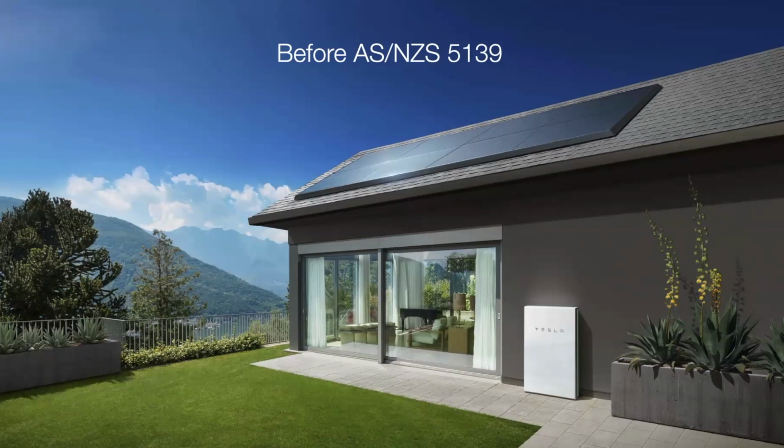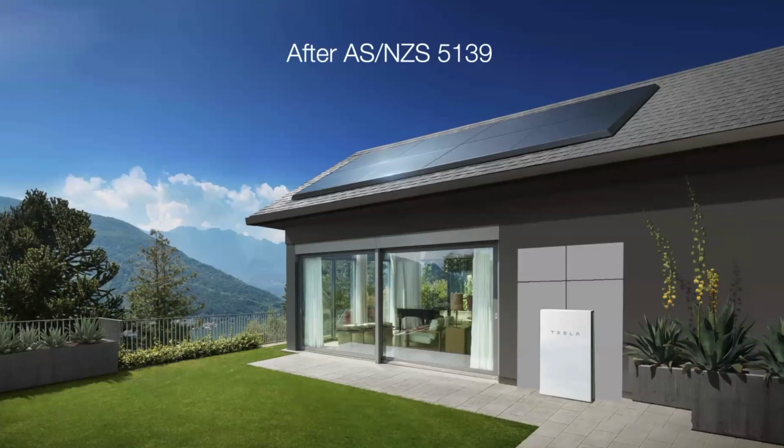Now, if that wall is not brick, terracotta, concrete, or a fire-rated material, let's say it's one of those super insulated SIP panels, it's not actually a fire-rated material, even if it's got a concrete render on it, that's not solid concrete. That wall would not be deemed a protection against the spread of fire, and there's a lounge room on the other side. So what would happen after 5139 is you'd be putting up a protection against the spread of fire.